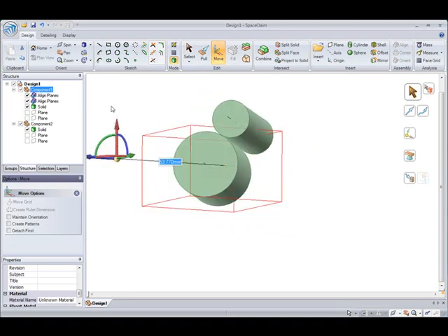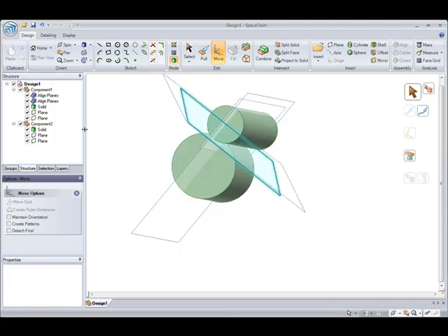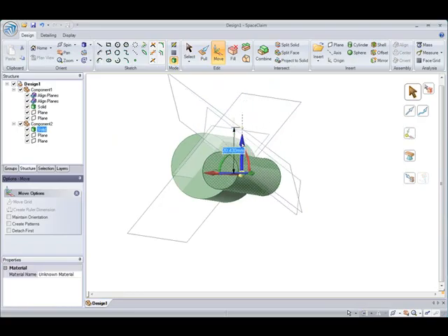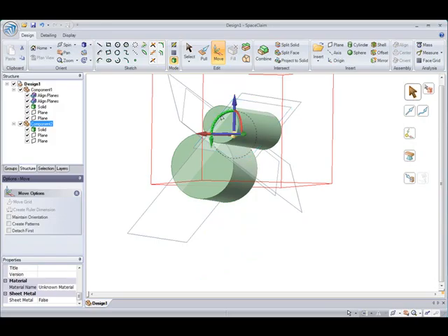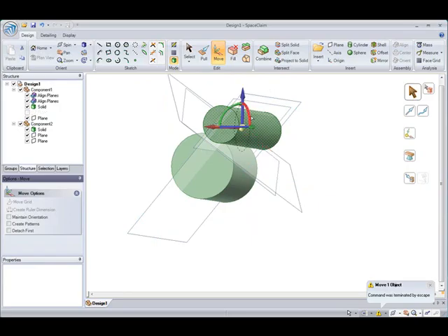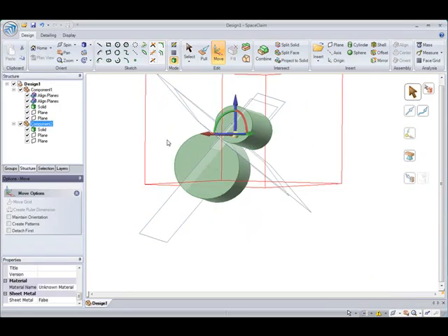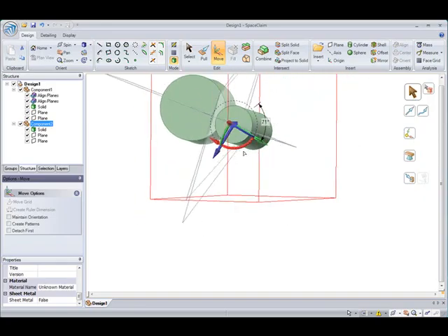The one thing to note here is that I don't have the solids aligned, just the components. So if you were to select on the entire solid that we have, I can actually move that away and break that tangency. So it's important to note here that all I've done is make the components aligned. And so you can see it a little bit better, I'll go through and take this component here, and I'll move it about the top of this. You can see how that stays around and rotates as I move it.